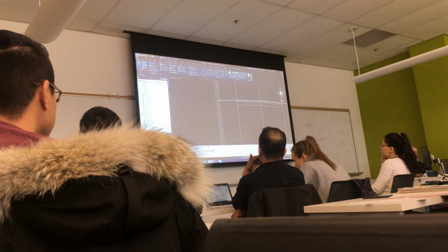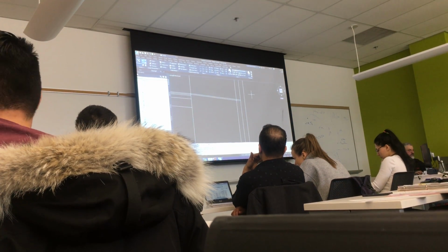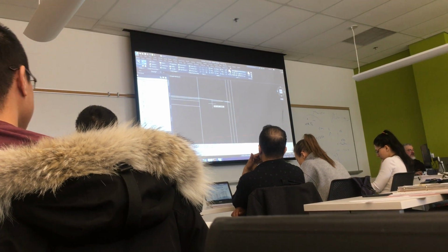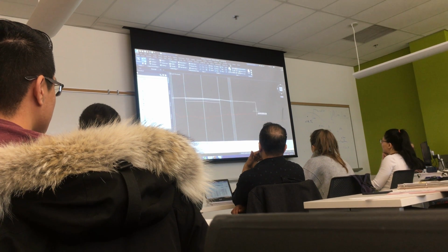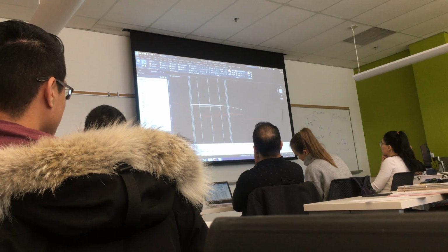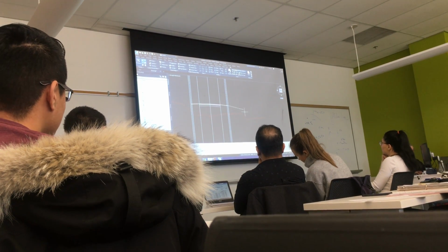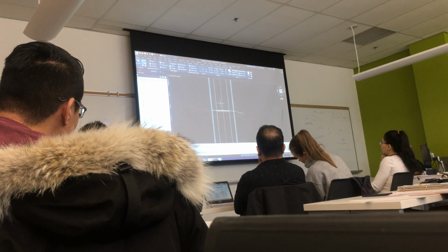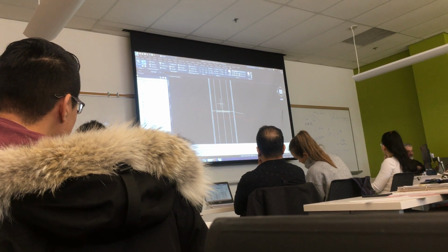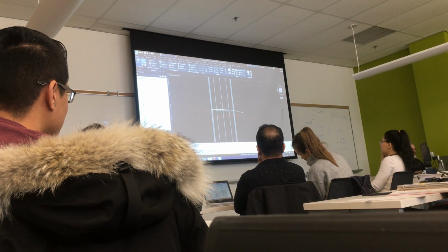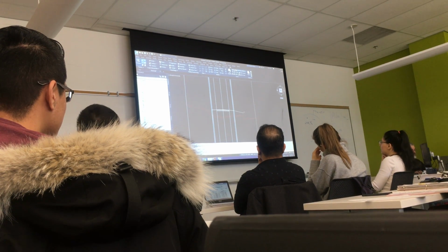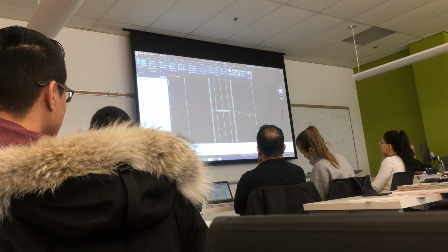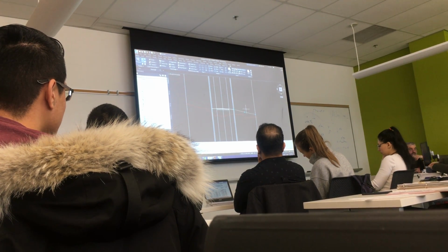Let's go back to CAD. So I'm going to draw a line from the center of the roadway. From here, I'm going to go over. How do you draw 6 to 1? You go horizontal 6, and you go vertical 1, and then you close that, and there's a 6 to 1 slope. And then, remember the property is 40 meters wide, 40 meter right of way, so I'm going to offset, just for reference, 20 meters from either side of center. There's my right of way. If I extend this, I don't touch the ground. So a 6 to 1 is going to be too flat.